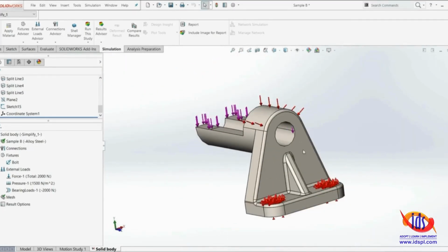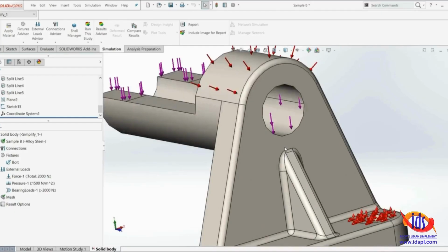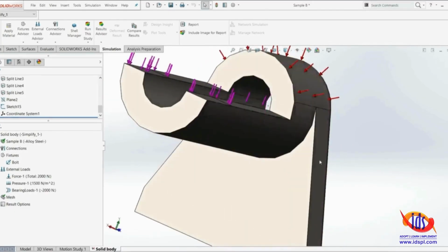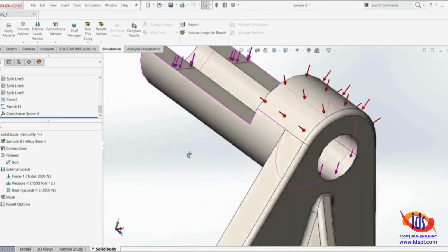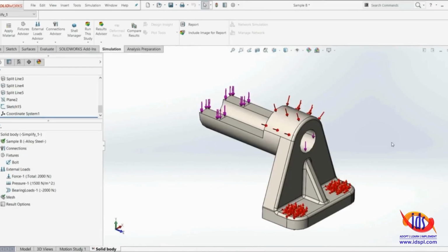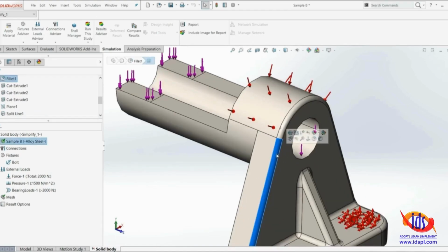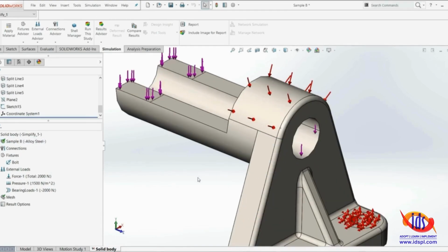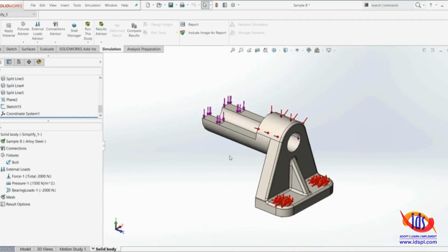SolidWorks, for solid bodies, uses tetrahedral elements with the ideal shape of 60 degrees and equal length edges, which have 4 nodes per element. So we want to maintain this shape as well. If you have a model with a lot of fillets, chamfers, holes, engraved text, you may want to get rid of those because those features don't affect the strength of the model. Due to this, the mesh on those features will be distorted and then you're going to get bad results.